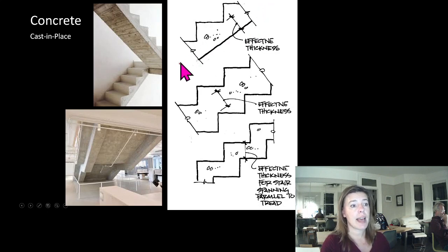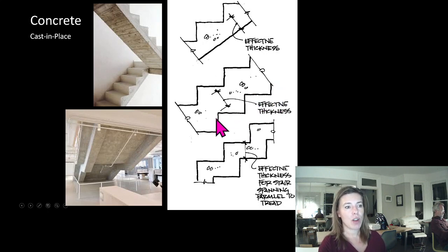This allows us to have relatively simple reinforcing. As you can imagine, it's just straight pieces of reinforcing. And for something like this, the reinforcing would be nominal, and the cost would be in how beautiful do we make these finishes. You can cast the underside, but this is now just some formwork. Well, not just some formwork. The formwork's going to be expensive, but there's cost in the formwork.